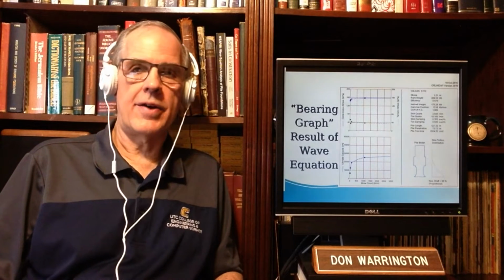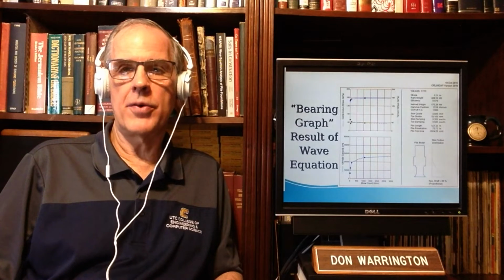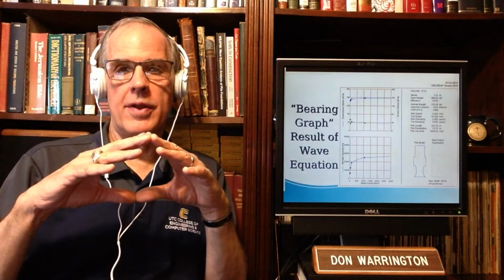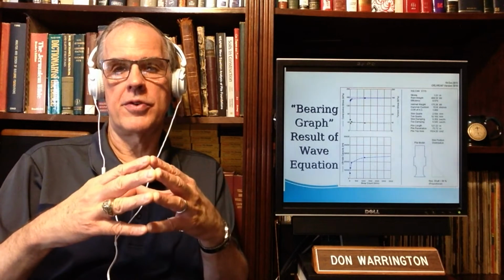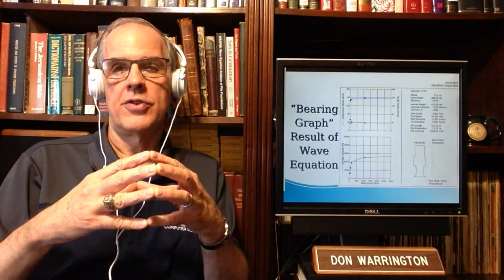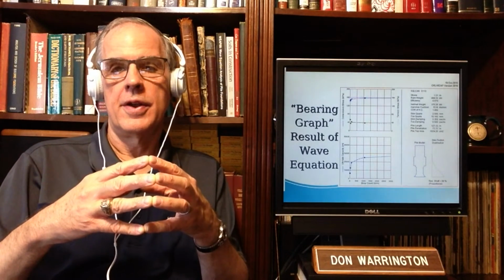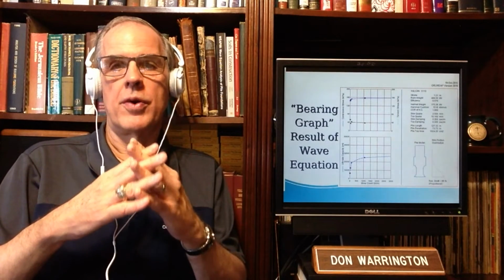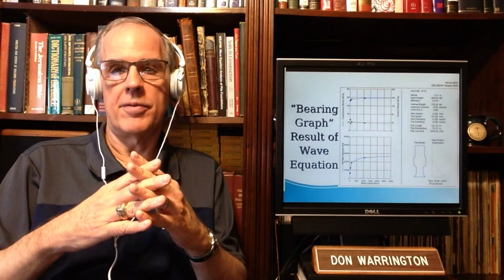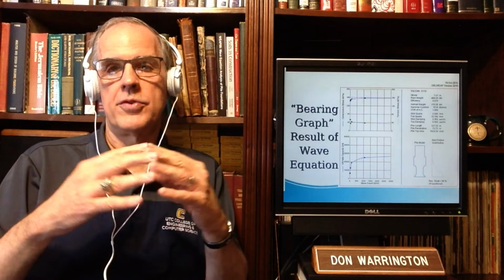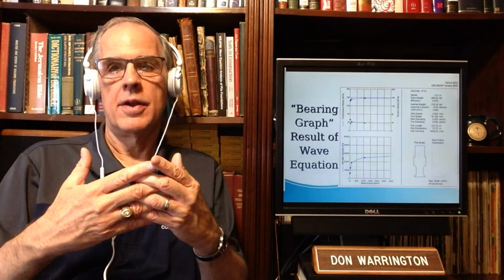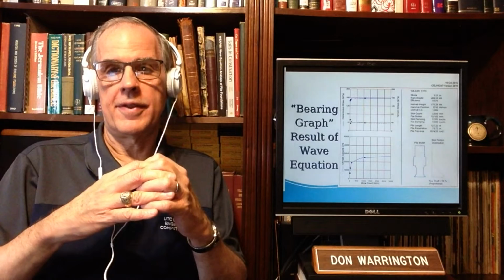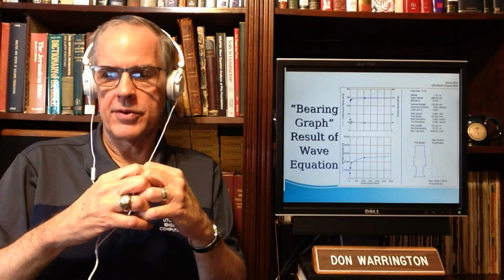To deal with this, we normally have a blow count criterion where we say that, well, we want 120 blows per foot, which I know is traditional for the Vulcan hammers. Sometimes you'll get 240 blows a foot for other types, and some DOTs do that. But you get a point where it's time to call a halt to driving when we get to that. In offshore, you could get much higher blow counts even than that, for a variety of reasons.